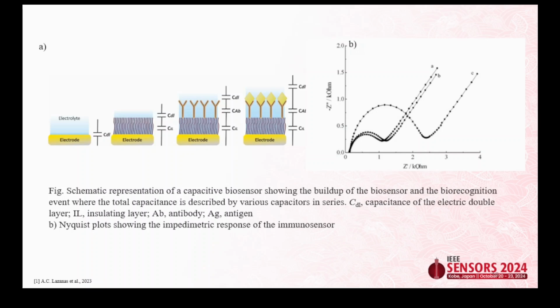of ions in our analyte, based upon the molarity or the concentration of the antigens that we are using. Ideally, if you see so many capacitances, there should be multiple semicircular graphs, but we are seeing just one semicircular graph. It is because the resistance involved in this case is very, very small, and there is no combination of RC circuit. This is a capacitive circuit, and in this capacitive circuit, just like resistance, Kirchhoff's laws also apply. So the capacitance that we are seeing is actually the impedance, and it gets added the same as the resistive values. That is why the change in the capacitance is the addition of all the capacitances that we are seeing with the change of the analyte concentration.